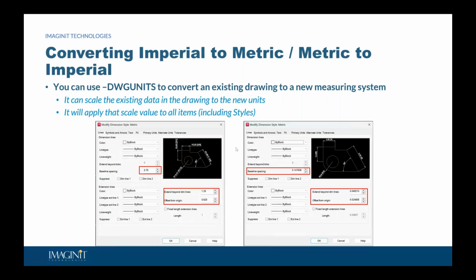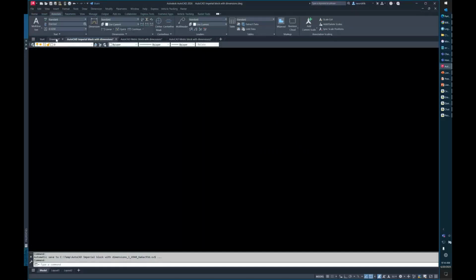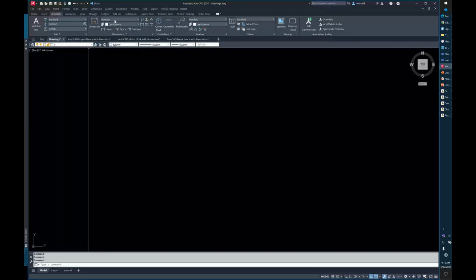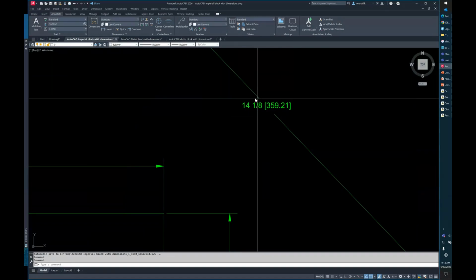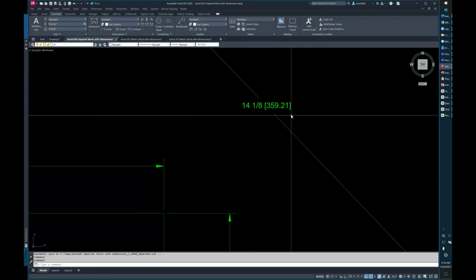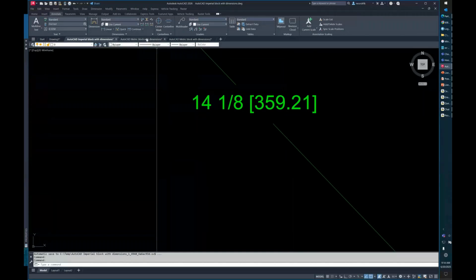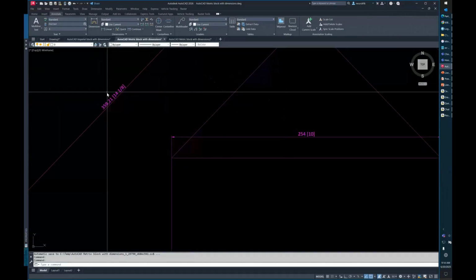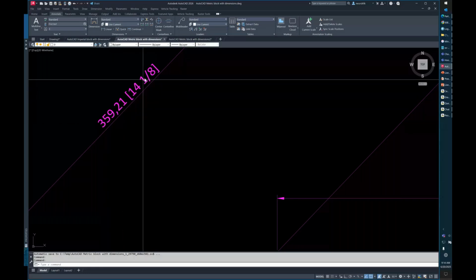And I have a good example to show you of some of these. Okay, so in my example here, I have just a basic drawing, and I have basic standard styles set right here, and I've not done anything with those standard styles except leave them as is. So I'm going to show you, this is the block I'm going to bring in. You'll see that this is set to fractional inches, and it has the millimeters as secondary dimensions on the end. I also have a metric block with dimensions, also with the same information, where I'm showing the millimeters, and in here I'm showing the fractional inches.